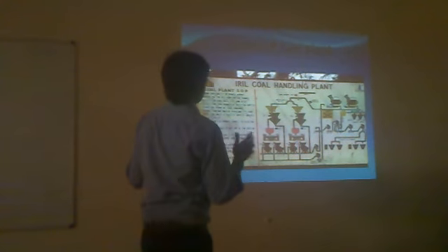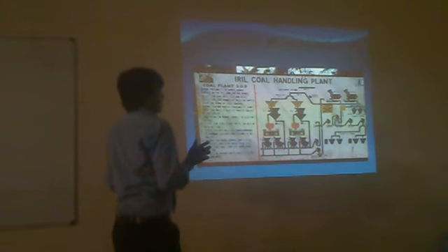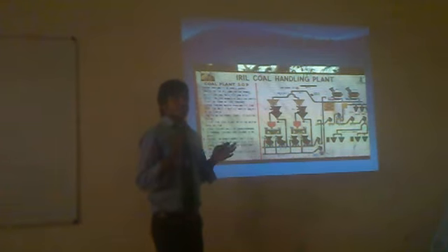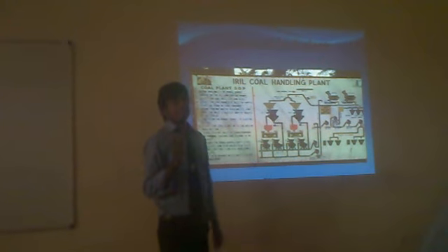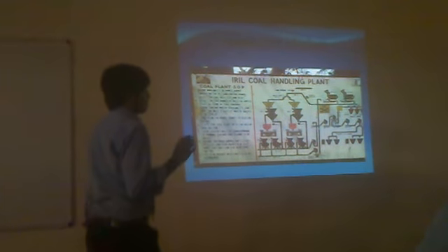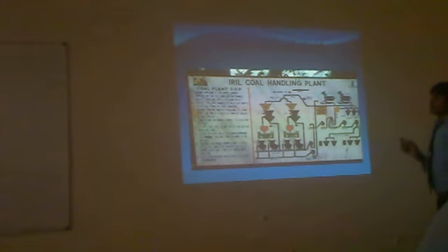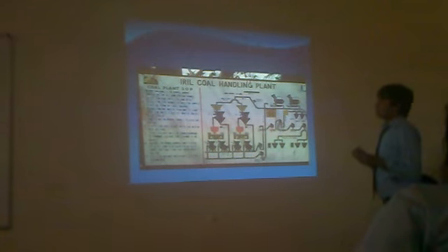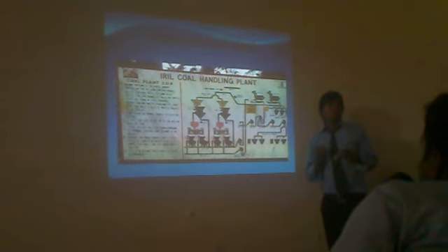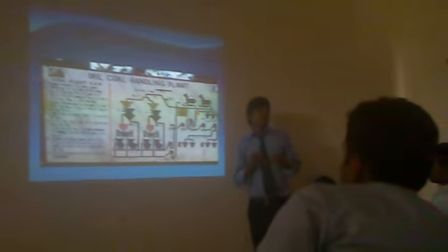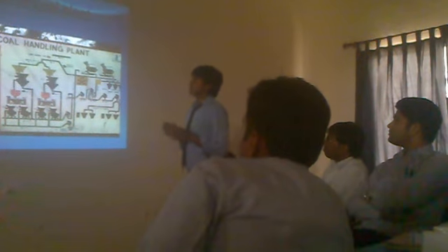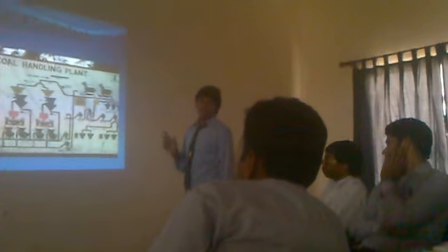So this is the layout of the coal plant. First of all, when the coal has come from the mine, it is too bulky and heavy in size. But in the power plant, they mainly require the coal at least minimum plus 8 mm to minus 6 mm. That is going to be used in the furnace.